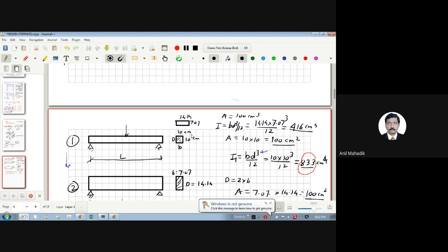So whenever you get a chance to change it, if your deflection criteria is not satisfied in, say, a building, समझो आपने एक beam design किया and the deflection is more, so what you will do? Increase the depth. That is the only way. Increasing the depth is a good choice. बहुत बार ऐसे होता है कि the architect forces you to reduce the depth due to their problem. So what you do generally, you increase the width, but many times you don't get much benefit out of that.